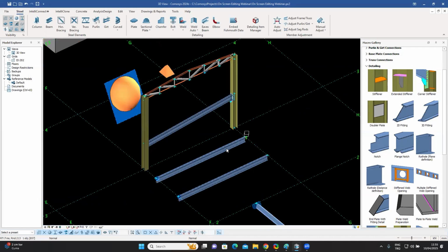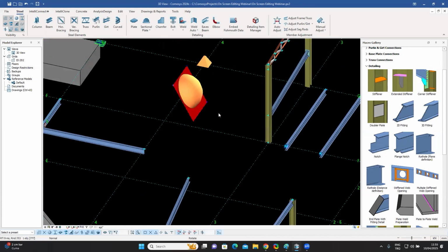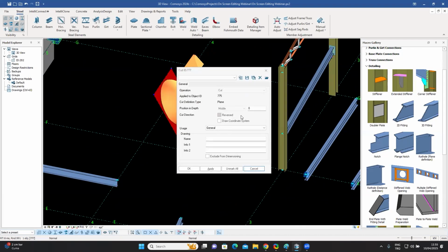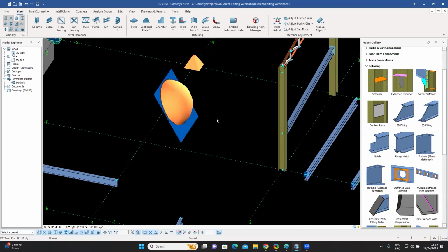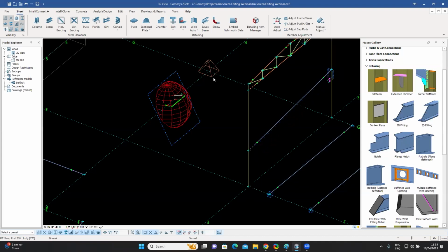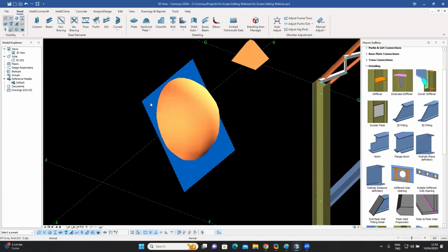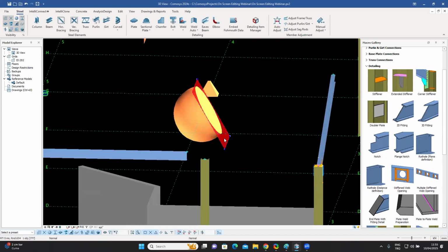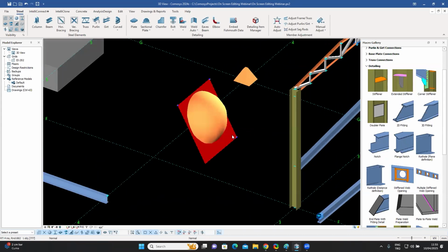The plain cut, which is a different cut, as you remember, is a new cut which was added in the last version. This one, as you remember, had the option of being reversed. So it would basically cut any object. Basically, it's cut a sphere right now, and it's cut the sphere according to a plane over here. Now, what I can do is if I select this cut and if I press Control Q, it will reverse the cut. As you can see on the screen, pressing the Control Q button will reverse the direction. So it's a quick, fast way of modifying it.